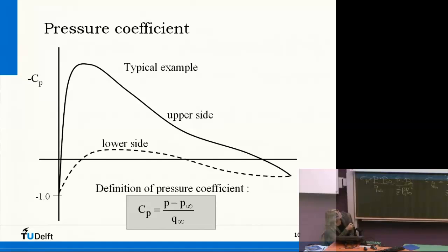So this is then the Cp on the upper side. Here is our stagnation point, right? So the leading edge, Cp of 1. Then what happens on the upper side and the lower side? On the upper side, we get very low pressures, the suction area. The suction peak is here, very high if you plot the minus Cp, and then the pressure increases again. On the bottom you have something similar but much less strong. And as you will see later, the lift is related to this difference.